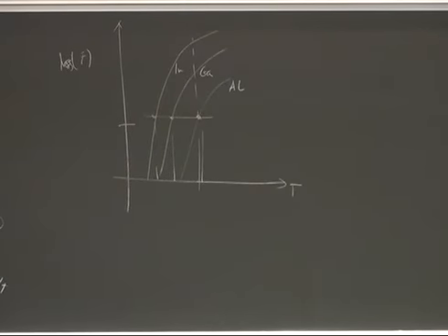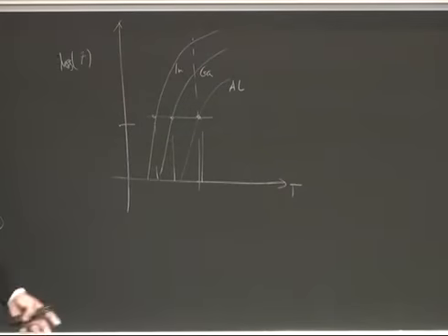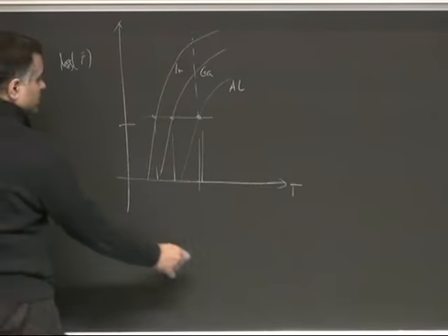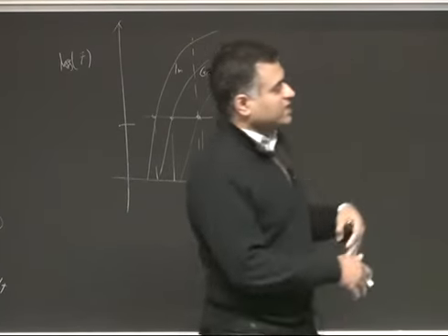But then you know that you have a lot of refractory elements, like molybdenum, which is very refractory. You can heat it to very, very high temperatures and you get nothing out of it. The vapor pressure is basically way out here. For them, this is not what you want. I mean, you can't get the temperature. Basically, the amount of heat necessary is not enough. For example, your wires can't carry that much current, and you start melting other things. So there are other methods that you use to get the flux out.